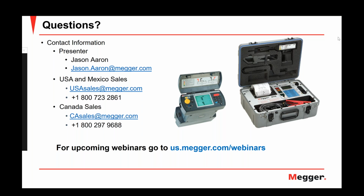All right. Volney, are there any other tests recommended for batteries? What are the equipments required in that case? And what are the IEC or IEEE standards? Okay, so as Jason mentioned at the beginning of the presentation, there are two electrical tests you can run on the battery to determine its condition: the capacity test or performance test, and the alternative test, the impedance test or ohmic value measurement.